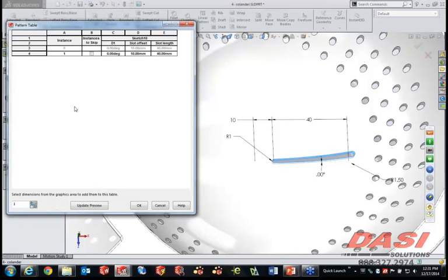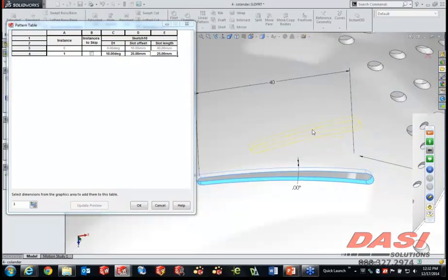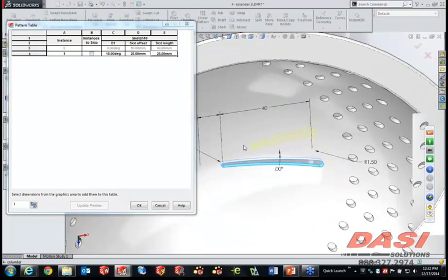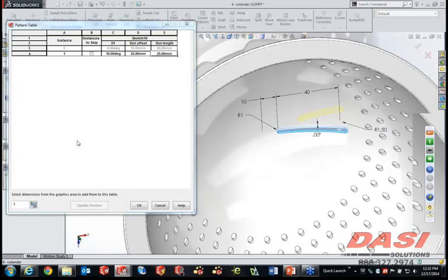We're going to add 1 row to this table and see how things look. Now I want to change the angle first of all. I'm going to change it by not really thinking too much and simply typing in 360 divided by 20. Hit enter, and just like Excel, you're going to get the actual math value of that. These other 2 dimensions, not quite as sophisticated. I'm just going to click and change each of those. Once I do that, if we simply update the preview, what you'll see here is the additional instance right up here to the top.